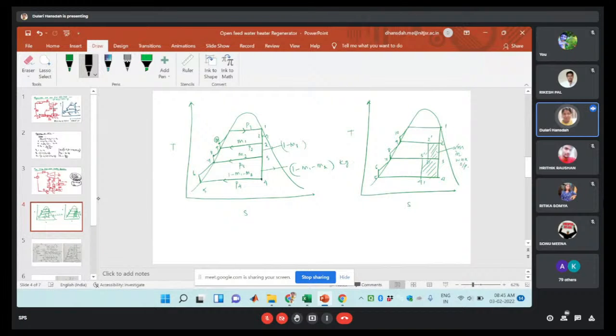So here there will be the heat loss. Let us take the heat loss as Q2. But in this case, the condensate will be obtained as the saturated liquid state. Then it will be pumped with the help of pump 1, 5 to 6, and it will gain temperature up to the saturated liquid by exchanging this heat, and then there will be a continuous process. Again it will pump like that, it will continue. Okay, so this is the regenerative cycle.